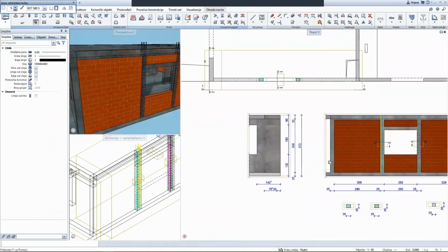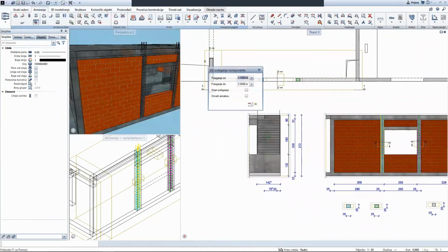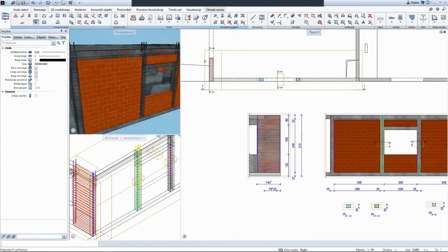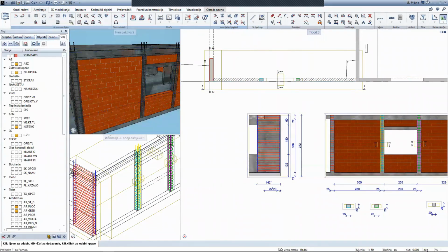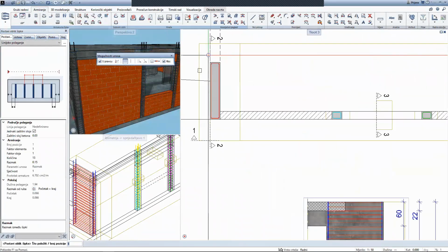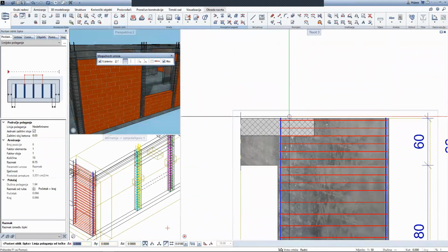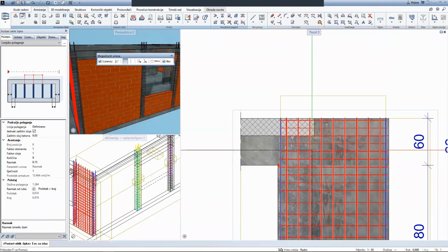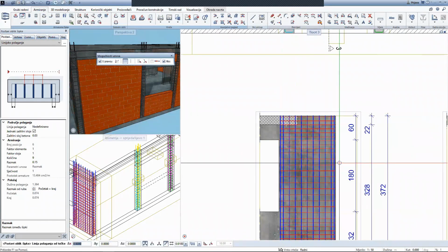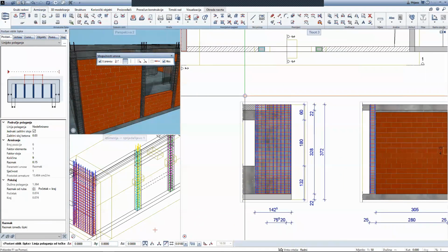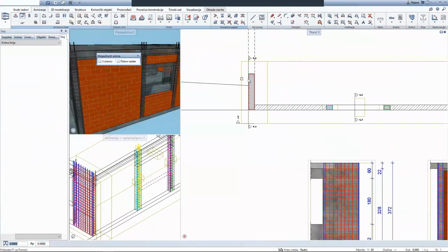These are coming with all the necessary reinforcement which you can adjust to all your needs. There are numerous types of it, like columns, openings, girders, foundations, and so on. First, we select the element we want and place it inside its section. After that, we define reinforcement parameters like diameter, quantity, bar spacing, and concrete cover. And those settings also, of course, can be easily changed afterwards.